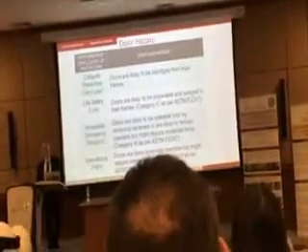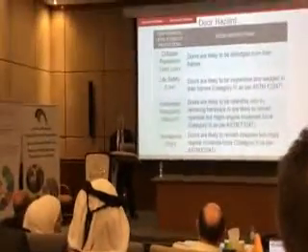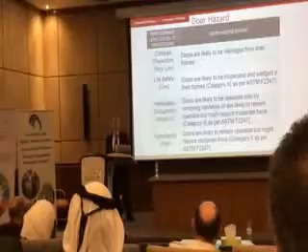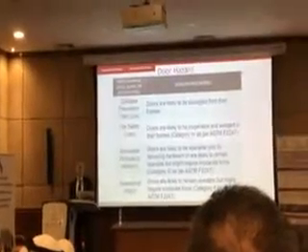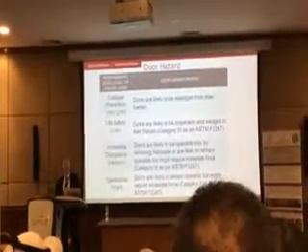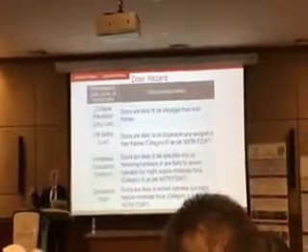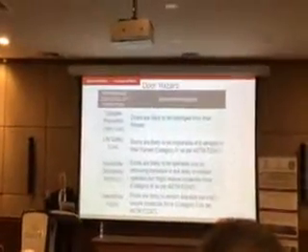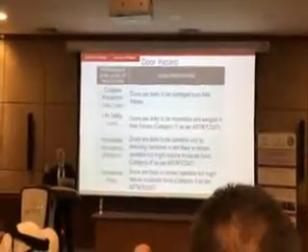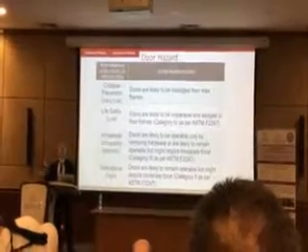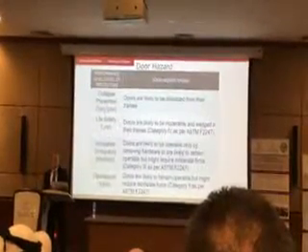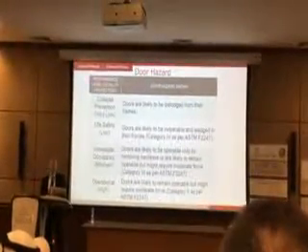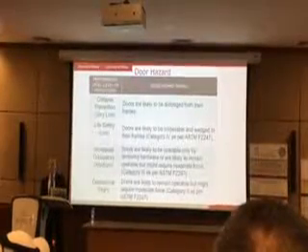And similarly, doors have different standards and different performance levels. For example, if it's a high level of protection door, it has to be operable after the event. After the blast, you should be able to open the door and leave. But if it's a low level of protection, so long as you can push it open, the mechanism need not work. So there are different levels specified in ASTM F2247.